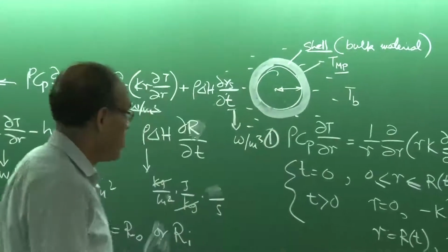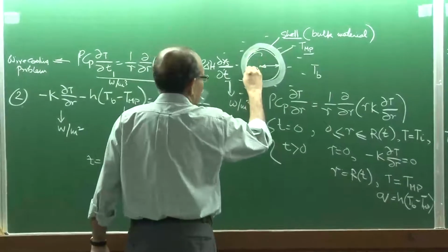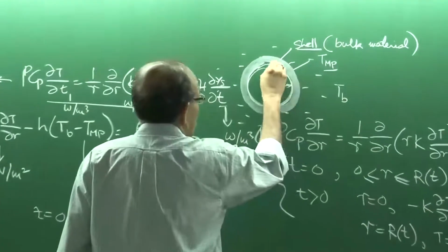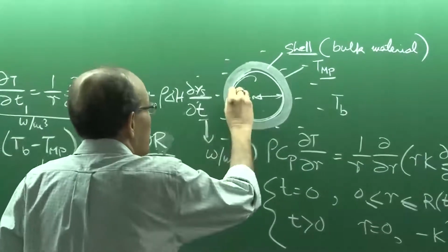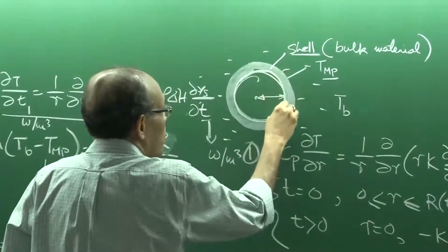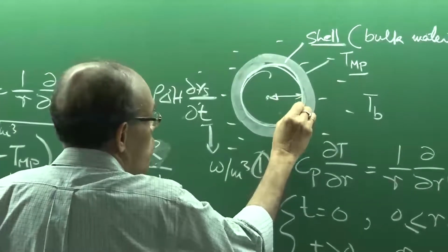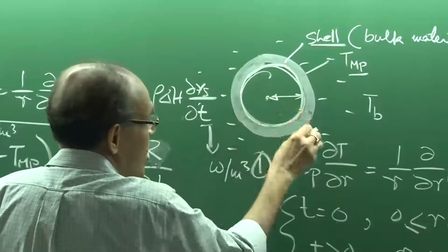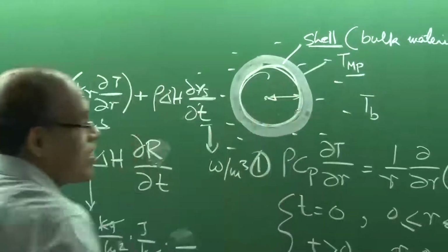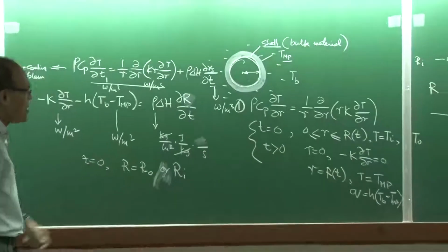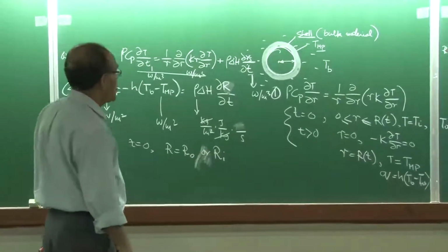These three parameters determine what should be the thickness of the shell which is produced on the wall of the solid itself. And we must understand that there may be a contact thermal resistance, because there are two dissimilar metals at this particular interface, which is a solid-solid interface nonetheless. This is a solid of the parent material, and this is solid of the bulk material, so there may be an interfacial resistance also. All sorts of complexities can be addressed provided you know the physics involved in the whole process itself.